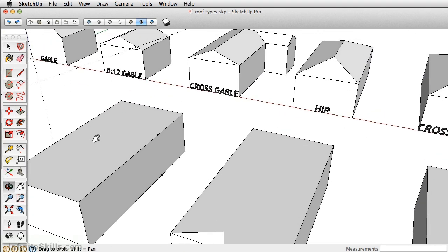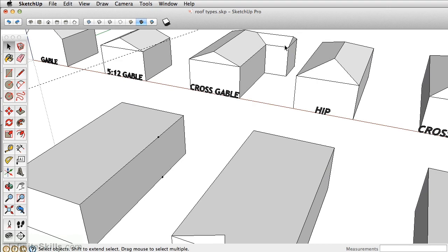The first thing that we need to do is create our little addition here. You'll see here that we created a guide that's going to allow us to draw a line. So take the line tool and just draw from this point here down in the blue axis to this point here. And you'll notice if you take the select tool, or the spacebar is the shortcut for the select tool, you'll see that it creates two separate surfaces or faces.